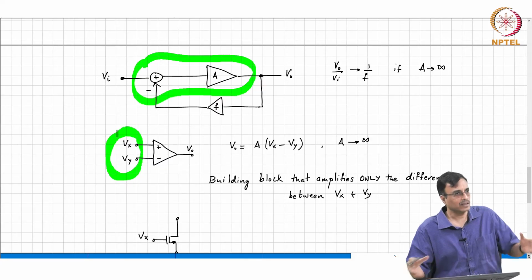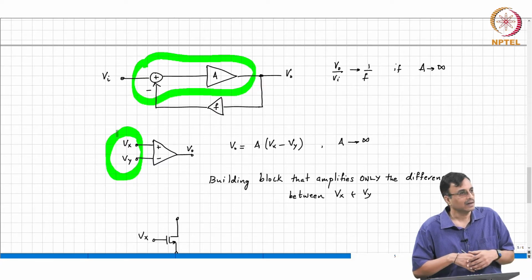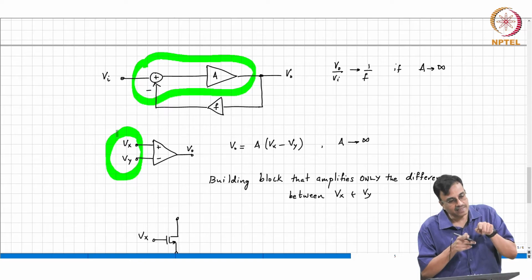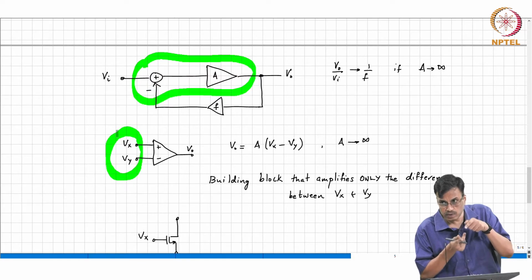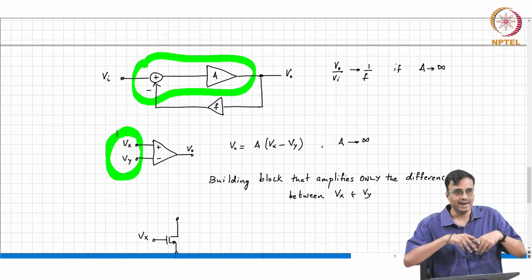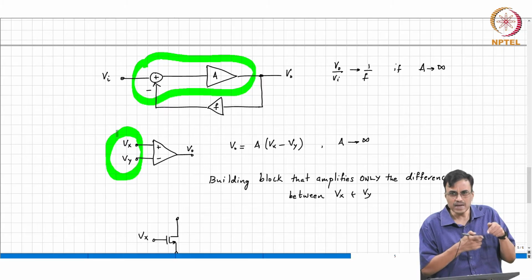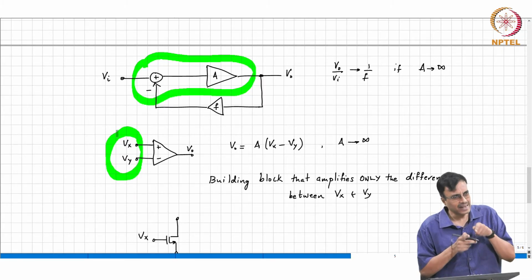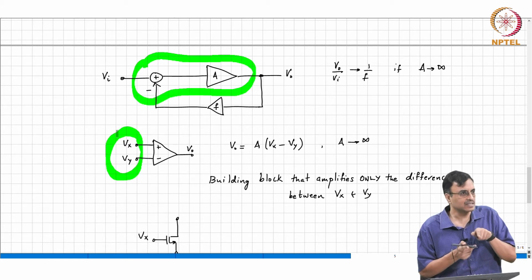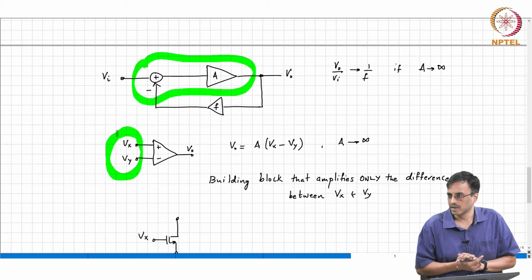Let us assume that we make this all work, and we indeed have a great operational amplifier. Once you embed the operational amplifier inside a negative feedback loop, what did we discuss would be the difference between the voltages Vx and Vy? Negative feedback is going to force that difference to be ideally 0. In reality, it is going to be a very, very small voltage, where that smallness depends on how large the loop gain is. Is that clear?